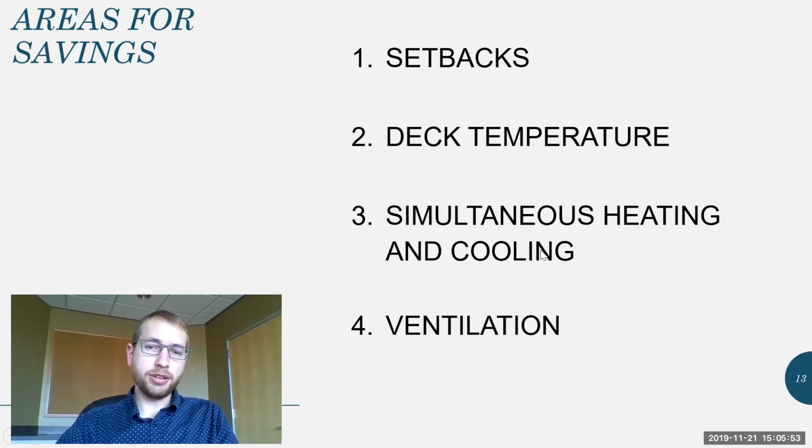Look for simultaneous heating and cooling. See if the cooling or the heating valves are stuck open. If they're both open at the same time inside the main plant, that could be a problem. Also check for it within the zone in open areas and make sure that you're only ventilating and providing fresh air when required to, and you're not spending extra energy conditioning outdoor air if no one's going to appreciate it.